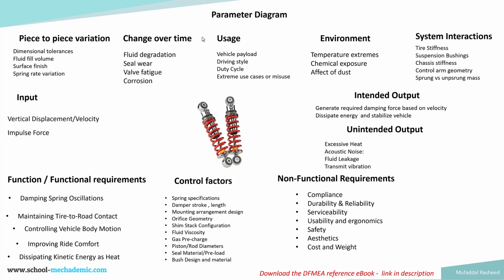Then change over time. So as time passes, as the shock absorber is used for years, the fluid degradation will happen, seal wear will happen, there will be valve fatigue and corrosion which will take place, that will degrade the performance. The third noise factor is usage.